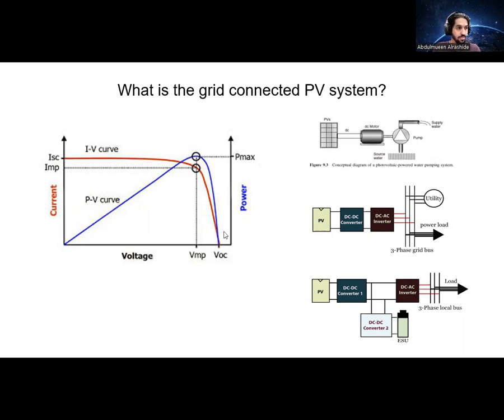And the second one is you apply the maximum current, or the maximum load, to the PV, and you see how much current it's going to give you. It's the short circuit current test. Basically, you short circuit the two terminals and you're going to get the maximum current. Now, this is the operating range for the PV. If you multiply the voltage with the current, you're going to get the PV power curve. And we're trying to get the maximum power point in this case.